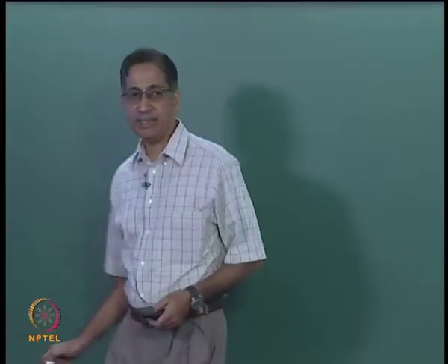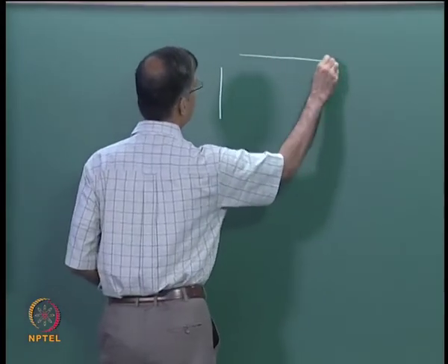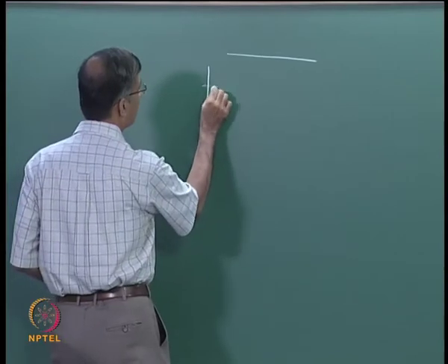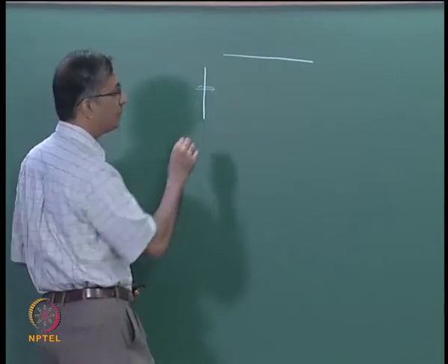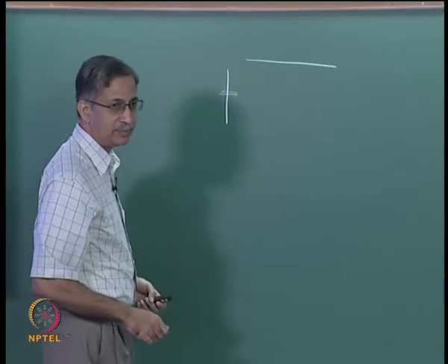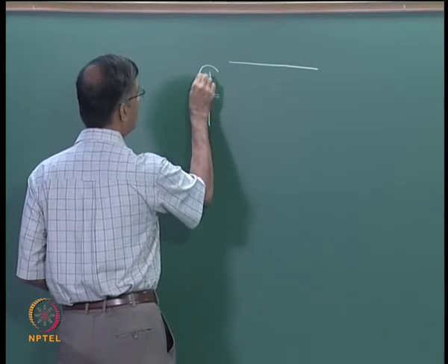So in your mind you must draw the free bodies. Let us take the top. You got a beam here, you have a column here. Remember we drew lines like this. So the column moment will be clockwise or anti-clockwise? It will be anti-clockwise, right?